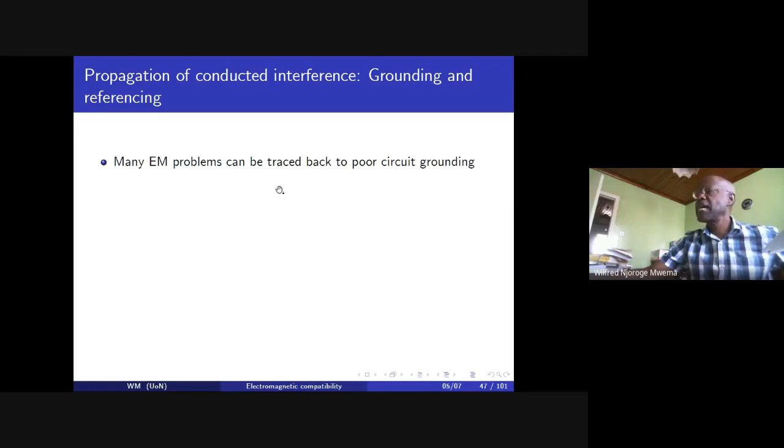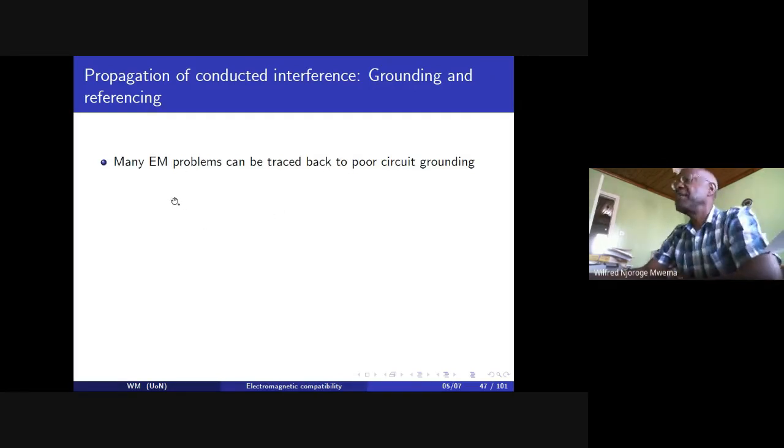And in many cases, you have that symbol in circuits, aligned with some short line, which looks like an arrow made of layers. You always call it the circuit ground. The circuit ground doesn't mean that it has zero potential with respect to another place. It only says that all the voltages in this circuit are going to be measured with respect to this point where that symbol is put. It doesn't say that the symbol represents 0 volts.